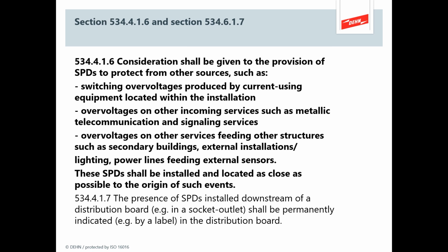And the wording here is quite key. These SPDs shall be installed and located as close as possible to the origin of such events. As I said, that's where the cable comes from the outside in. You have to nip the surge in the bud at the origin of the event itself.